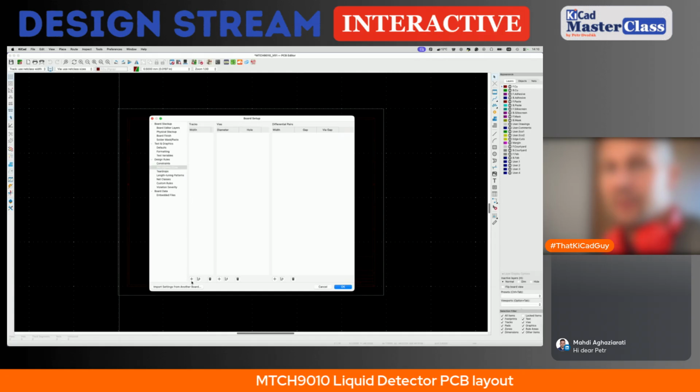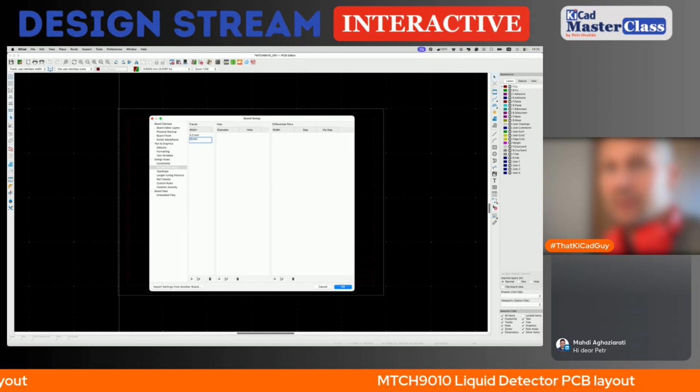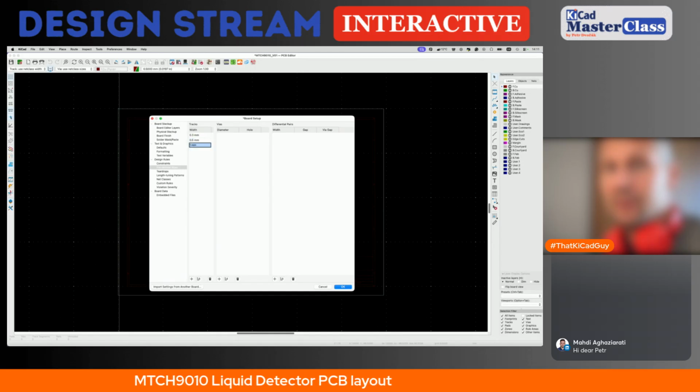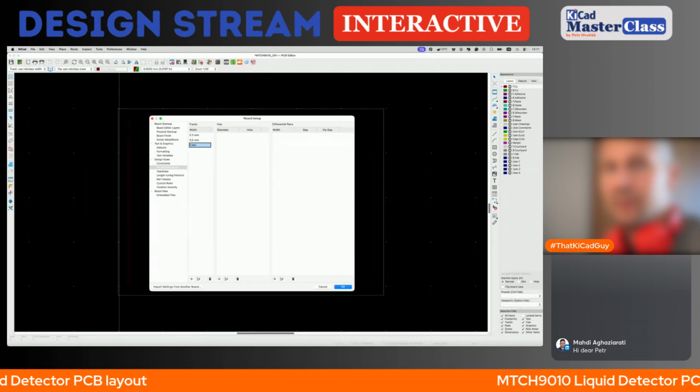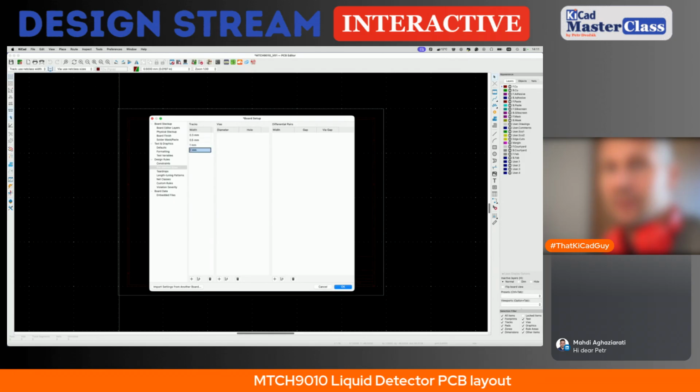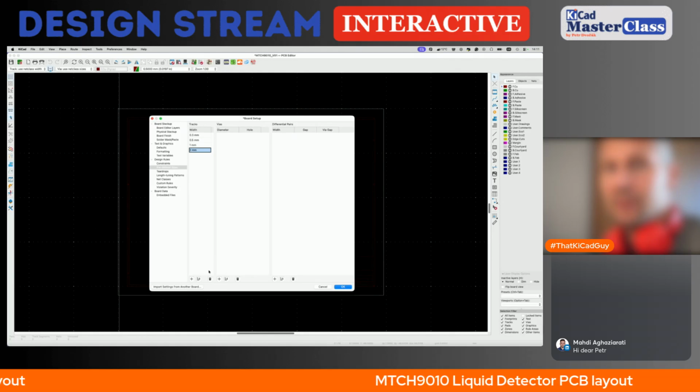Tracks, yeah, I think besides the default net class, I will use 0.3, 0.5, and maybe 1 mm for something. At least for electrodes, if there are some special needs, and 2 mm as well for the electrodes. I'm not sure if 2 mm is not so thick, but we will see.